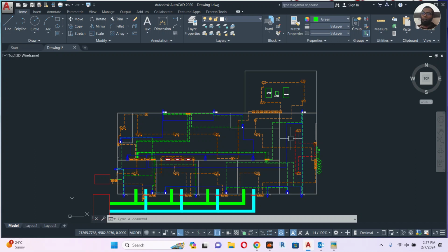So for the telephone data rack, you can put one module. Sometimes they request, and you have to check everyone. You have to go to the mechanical people. You have to check with them what kind of modules you need, where you need fire alarm. If you have a telephone data system, you have to check with them. CCTV, you have to check with them. BMS, you have to check with them.